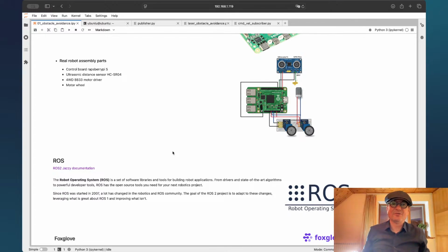We should install a couple of ultrasonic sensors at the bottom of the robot, in front, pointing down to detect stairs.